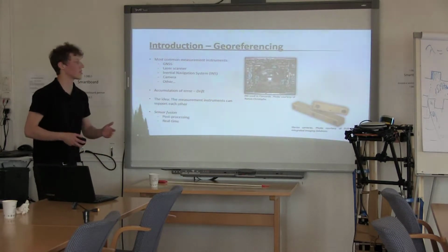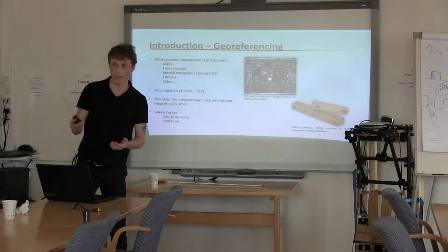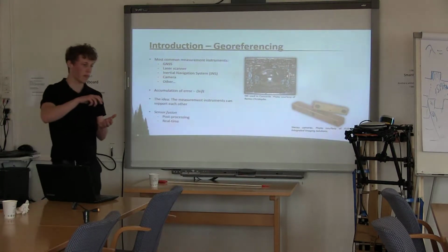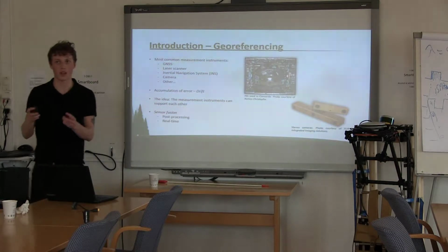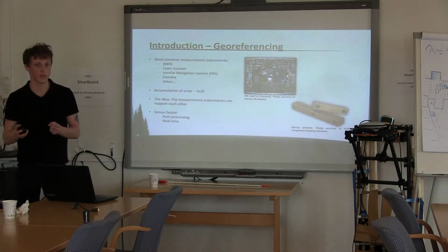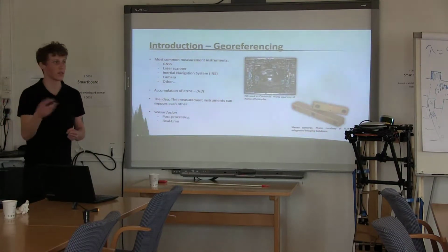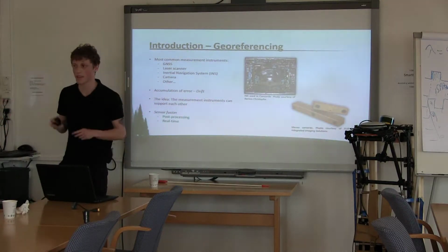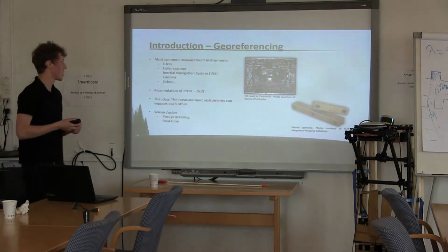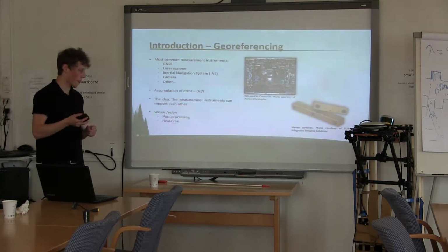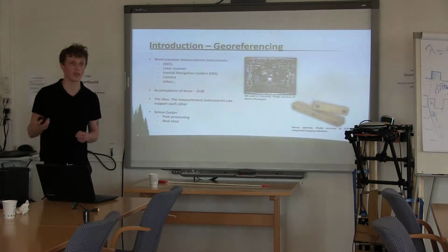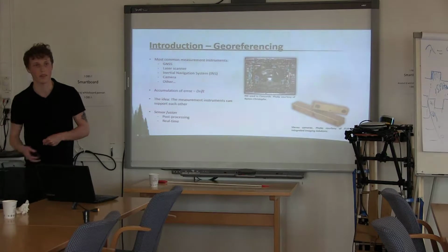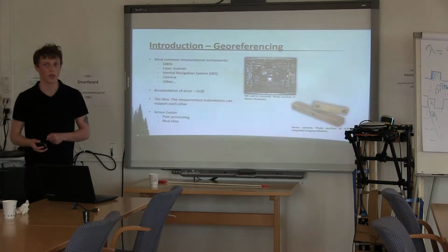But the idea is, if you combine instruments like a GNSS and an INS, you can sort of make them support each other, so that when one instrument struggles, another instrument can be given more weight and can take over, and vice versa. And this is usually referred to as sensor fusion. And it can be done either after you take measurements, in post-processing, or in real time.